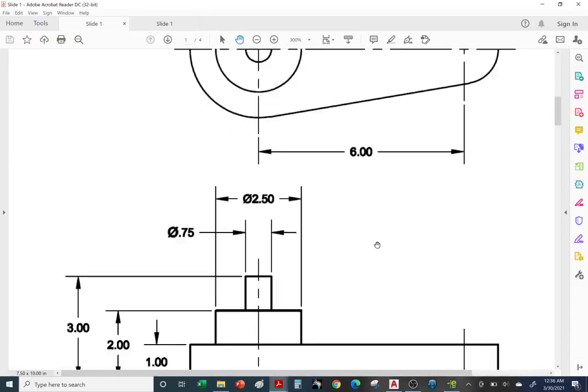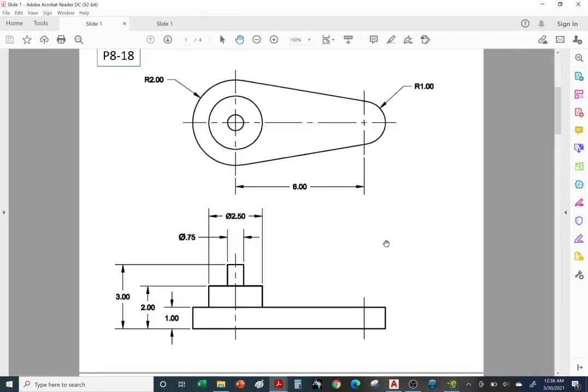Yes, we're cheating. Take a look at the answer key. We have all our green center lines, all our dimensions. And again, notice how everything's grouped. We go from small dimensions to larger dimensions, right? You want the older siblings outside and the little siblings on the inside. You don't want them to get cold. You have the larger, older siblings protecting the little ones, right? So you go from small to large in most cases, 99% of the time or 90% of the time.